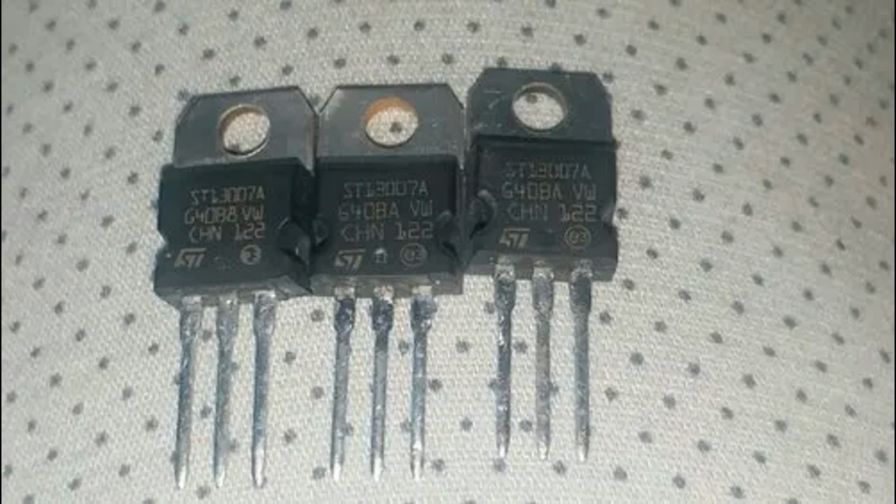Switching is another fundamental and important application of transistors in electronic circuits. Transistors can act as electronic switches, controlling the flow of current between two of their terminals in response to a control signal. This on-off behavior is the basis for digital logic circuits and plays a critical role in a wide range of applications. There are two primary types of transistors used for switching: bipolar junction transistors, BJT, and field effect transistors, FET. Here's how transistors are used for switching.